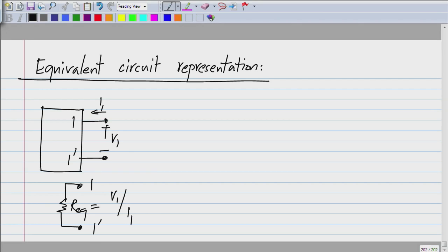So my question is now we have to do a similar thing for two port. That is, this very simple circuit is the equivalent of this whole box, whatever complicated circuit be inside. As far as these two terminals are concerned, that is very important. When we say it is equivalent, we should find out where is the equivalence. These two terminals, the voltage current behavior will be the same as in this complicated circuit. Inside this, you could have hundreds of resistors and linear control sources and so on. So all of them will finally reduce to this linear relationship between V1 and I1.